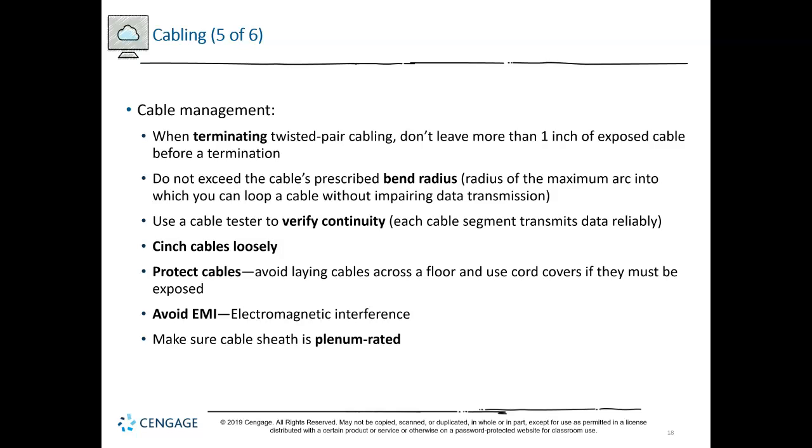And there's something about here that says plenum rated. Plenum really means just airspace. Everybody in here likes to breathe, right? Yeah, I hope. But in here, when the air conditioning runs, notice there's these air returns in places. It just sucks up into the top of this airspace, right? So there's ceiling tiles and it just goes up into this airspace. So that's considered plenum space. It's airspace that you can breathe. Well, we have a lot of cabling up there.